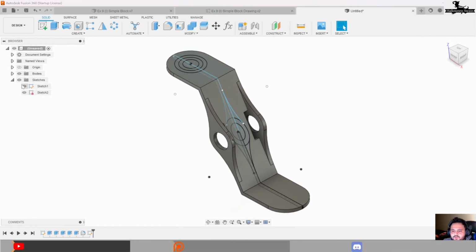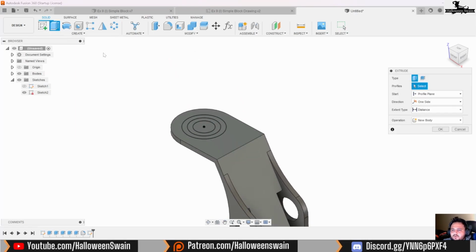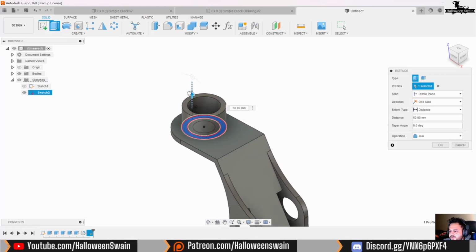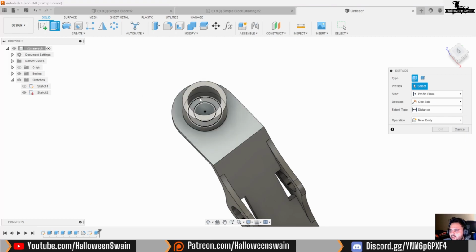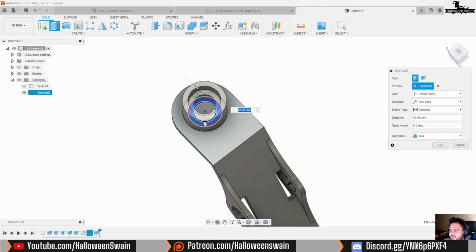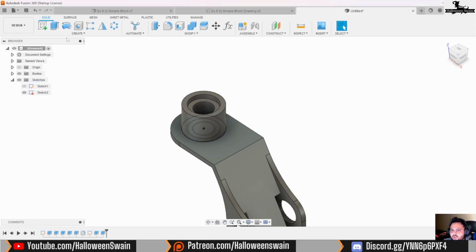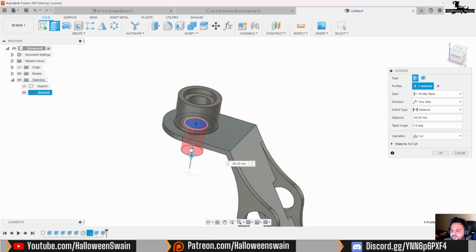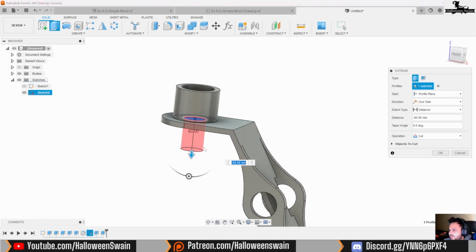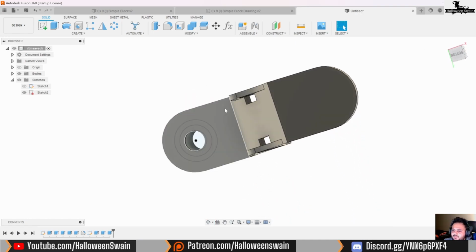And we are going to turn on the sketch, this one, move it down. So we're going to start extruding the first one to 60, and that is done. We are going to start again with the second one, use up to 40 or use 50, use a join. Now again one more time. This time we are going to go down in order to make it hollow, like a proper cut. Here we go. So as you can see, this one is pretty much done.